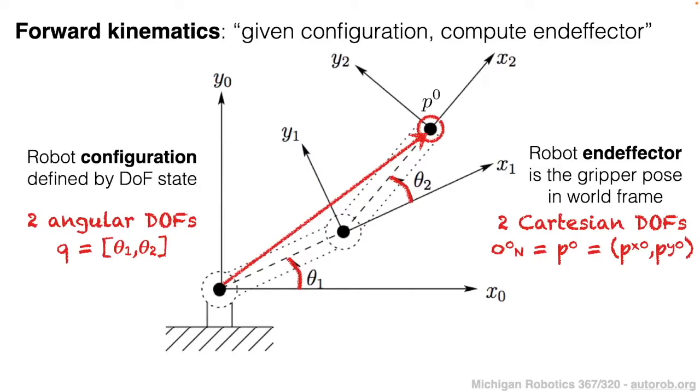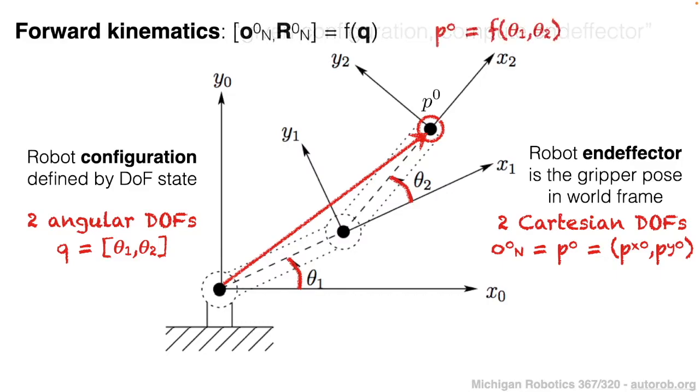All right. So to summarize forward kinematics, the whole purpose behind it was to say, here's some given robot configuration. So here are the joint angles of our planar two-link robot, right? So let's say that theta 1 takes on some value, theta 2 takes on some value. I want to be able to compute where the end effector is within space as defined by the world coordinate frame. And so from that given configuration, what we want is some function that will produce the position and also the orientation of our end effector within the world coordinate frame, right? So the whole purpose behind forward kinematics was to say, here's some configuration, apply some function f, which in our assignment 3 was our recursive forward kinematics routines, in order to produce the resulting position and orientation of our end effector in the world coordinate frame.